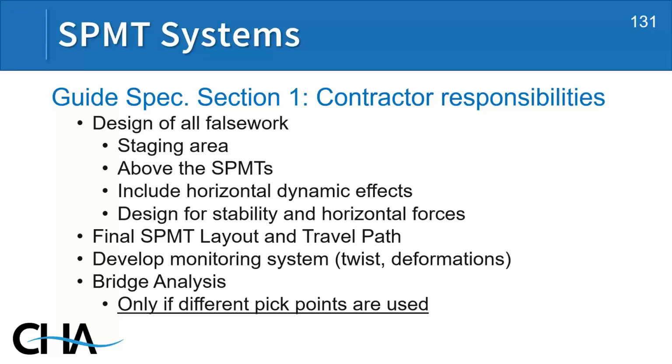As far as bridge analysis goes, early SPMT projects required the contractor to analyze the bridge. We prefer to have the designer analyze the bridge because the designer knows the bridge system much better than the contractor. But we do say that if the contractor decides to lift the bridge at a different pick point than what's shown on the plans, then the contractor needs to analyze the bridge for those new pick points.